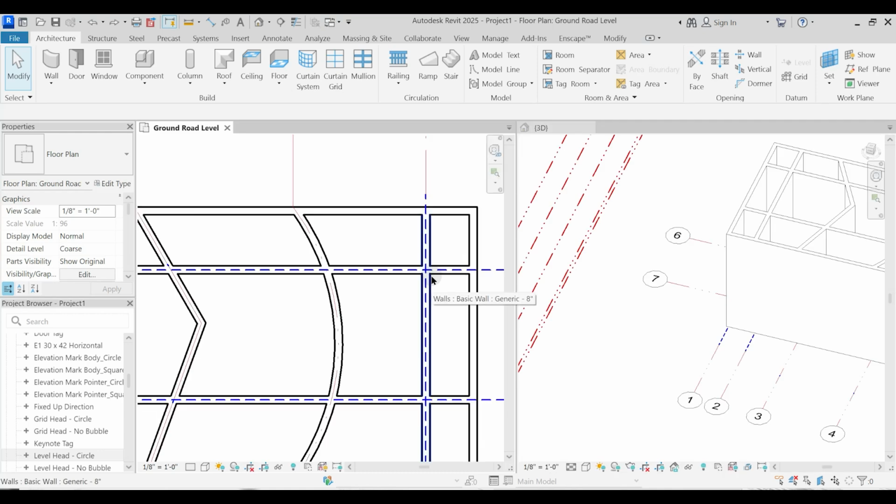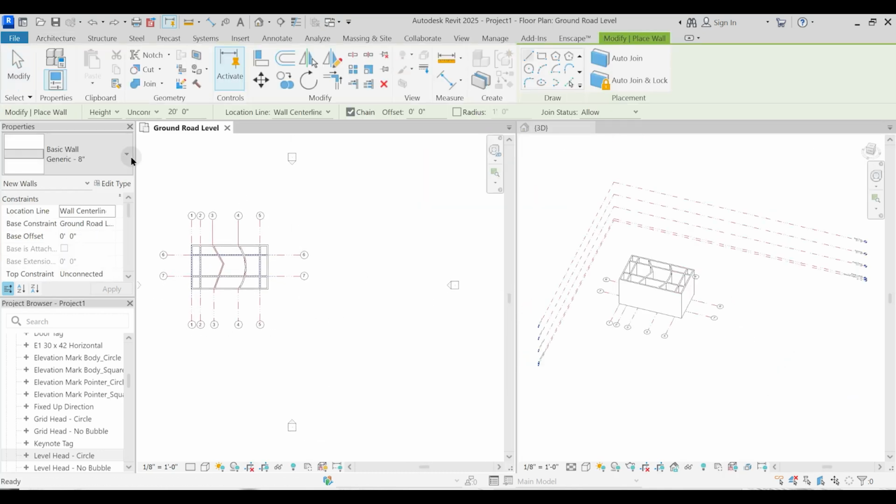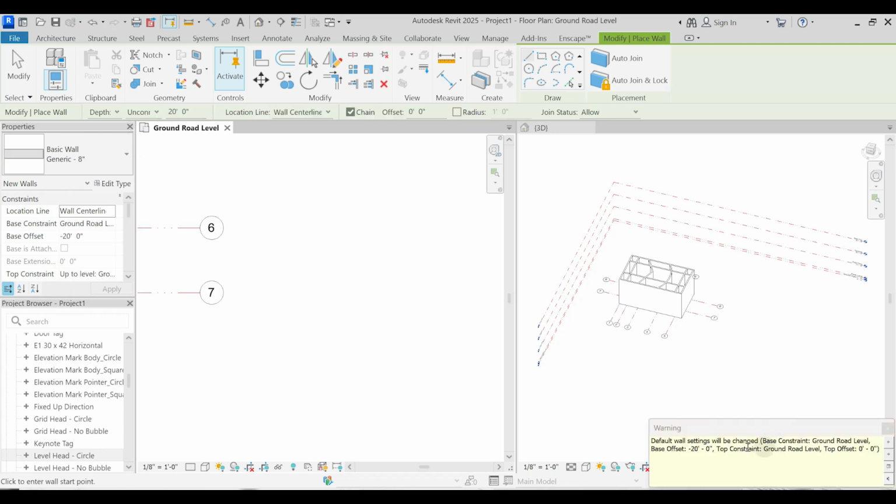So I'll just click WA. Fine. I will just click this WA. Okay, and generic 8 inch wall. Fine. So you see that these different parameters pop up. Instance parameter. In your case, if this particular thing is changed to depth, then just change it to height because depth में तो जाना नहीं है. If I just select this depth, then you see that it pops up this error. ये error pop up होगा. So this should always be height.